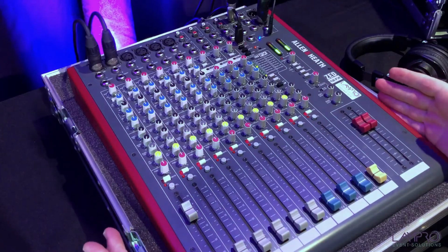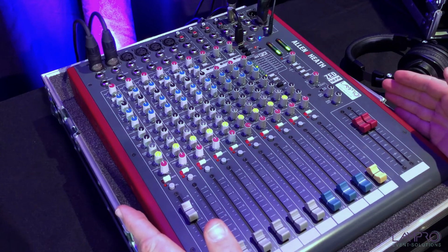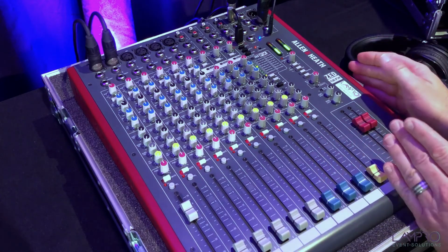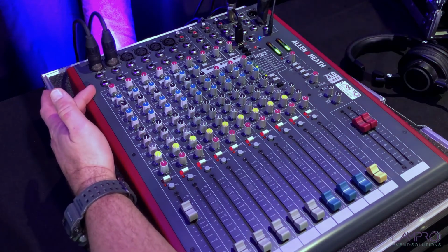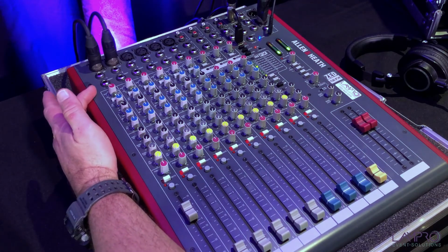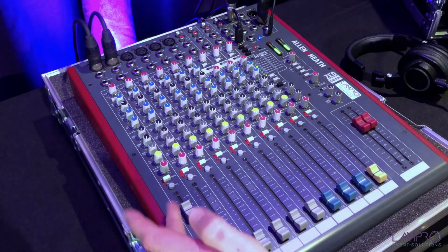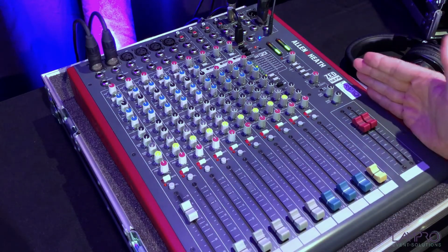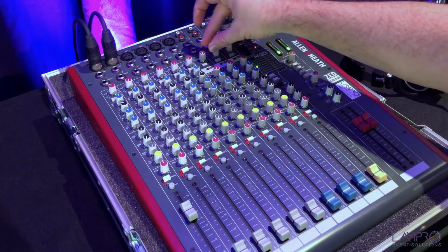In front of us here, we can see the Allen & Heath Z12 effects, and this is a good quality standard analog mixing console with 6 mono or mic channels, 3 stereo channels, and the effects unit that's also built into this mixer. You can see on channel 1 at the moment, I've got my microphone connected that's being used for the recording with the gain that's been set properly, the EQ that's been set, and the fader at the bottom is open that will send the audio from this channel to the master outputs that's being used for the recording. From the onset, it's always important to remember to have all of your gains set up properly.